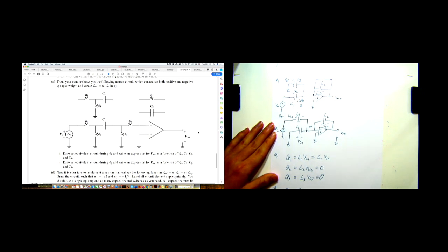So, in this case, since you have ground on the left plate and kind of virtual ground on the right plate, it's 0 volts across the capacitor, right? So you have like 0 charge. If your question is how do you determine how to take the Q equals CV, then because Ricky labeled plus on the left and minus on the right, when he's saying Q1 equals C1 VC1, he means that on the left plate you have a positive charge of Q1 with this kind of nomenclature.